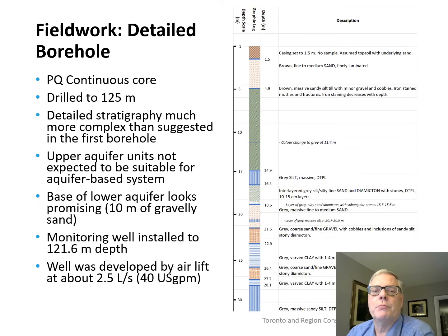Based on that initial borehole, TRCA elected to drill a detailed continuous core hole using PQ core down to the bedrock surface at about 125 meters. And what this detailed core hole revealed was much more complex stratigraphy.